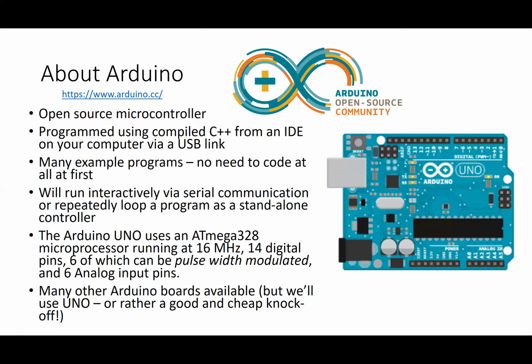Now we go to the next star of our show, which is the Arduino. It's an amazing little thing. You can buy an excellent knockoff board, which isn't really a knockoff board because all of the design for this is open source, but you can buy a board for about $10. If you want the genuine Arduino, you're going to have to wait a long time for delivery and pay about 3 times more. But here it is. This little board has a microcontroller, a USB port that you can communicate with your computer with, a power plug here, and then actually serial lines here that will let it communicate with other chips and so on.